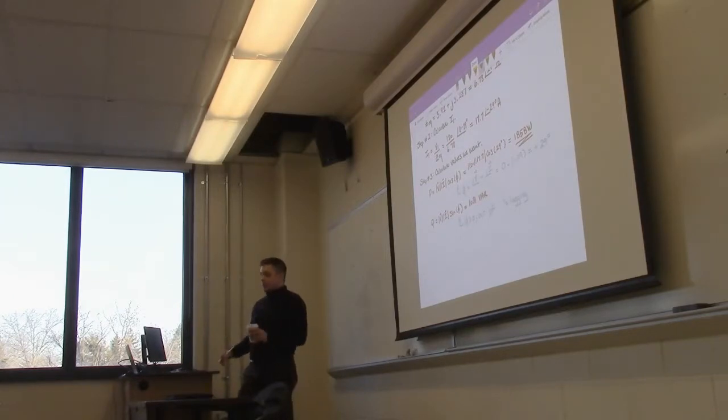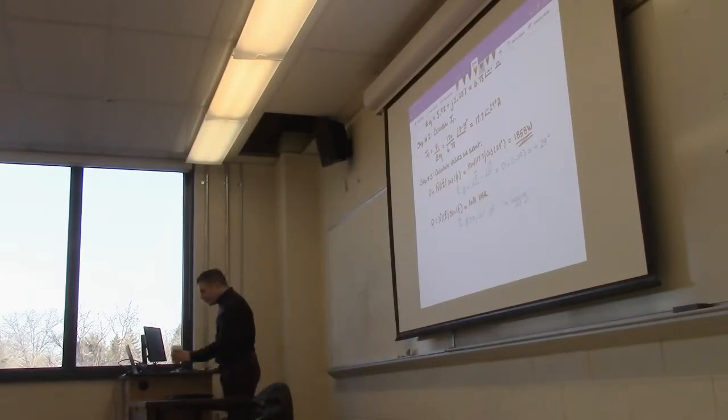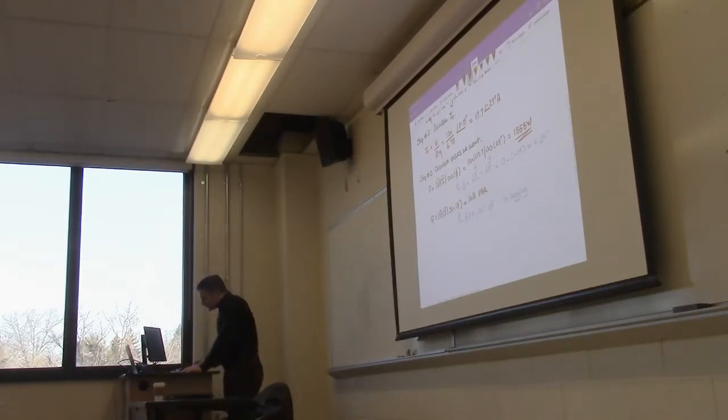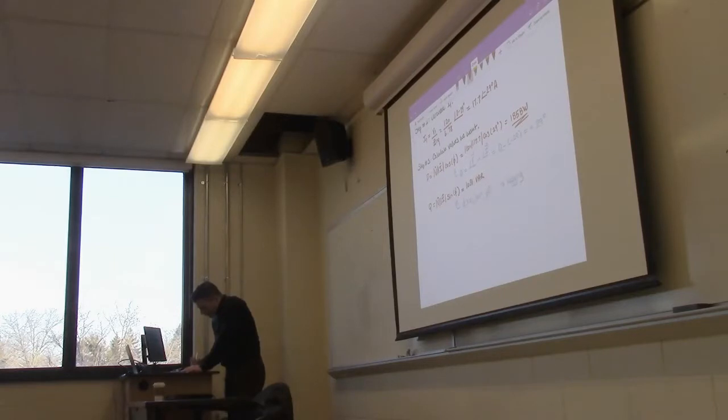That was basically my question. So if you have leading power factor, that means you're going to have to use inductive elements as opposed to capacitive elements in order to push the system back in the direction. Okay, next. S is pretty straightforward because we have our P and our Q.